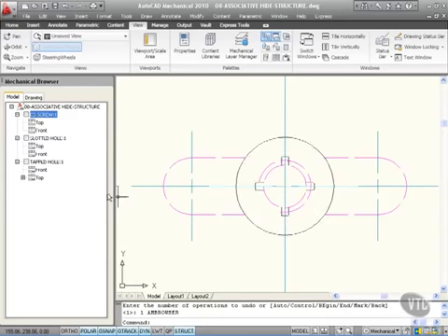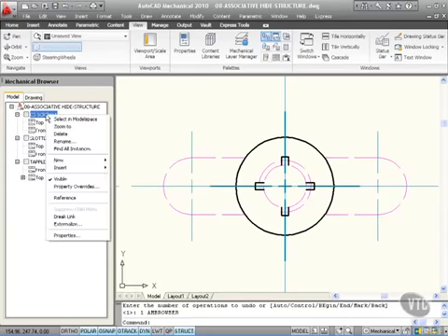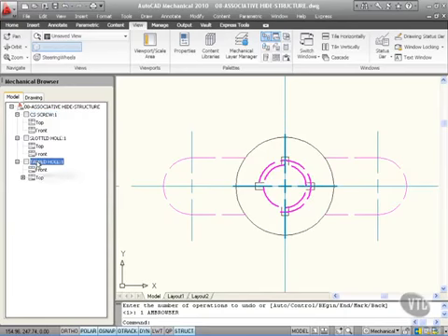So how do we change this? How do we change our visibility views using our mechanical browser? Let's have a look at the countersunk screw there. What we need to look at are property overrides and whether it's visible or not. If I go to tapped here and just make that invisible, unfortunately it's overridden the countersunk screw there. I need that on top. So what I've got to do is somehow work with my hide and with my mechanical browser to get this to work so that when I'm using a structure, everything appears on top.